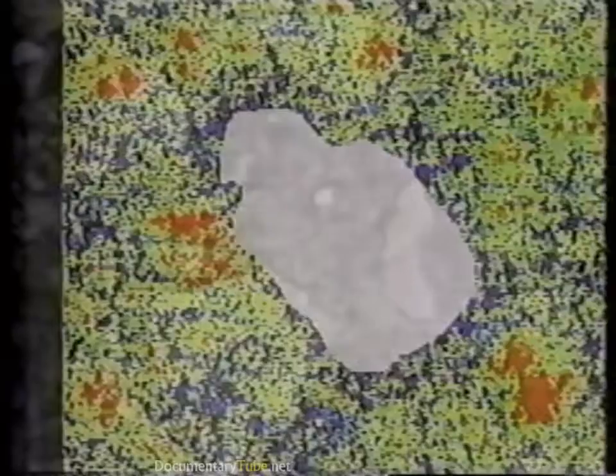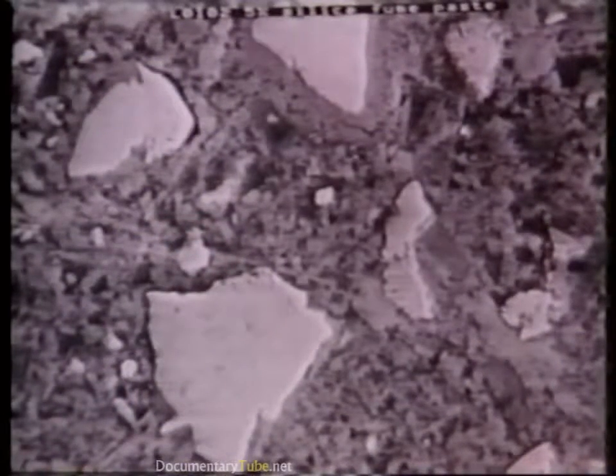After a cycle of dissolution, diffusion, and precipitation is complete, the computer proceeds with another cycle. As this process repeats again and again, the microstructure develops, building bridges between particles that provide strength to the material. Computer simulation has proved valuable because it allows researchers to test conditions and make measurements that are difficult to achieve in real life. At the end of the hydration simulation, the structure of the hardened cement paste is very similar to that observed under the microscope.